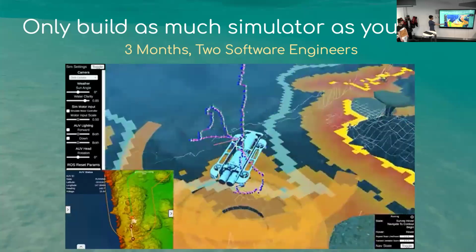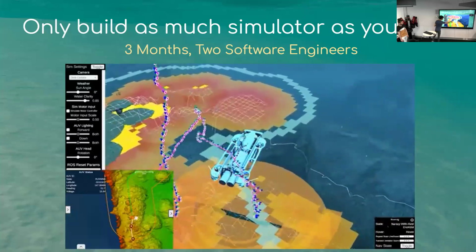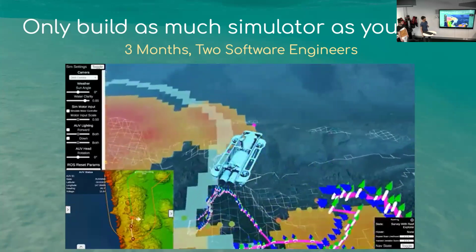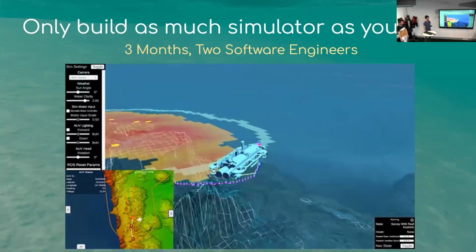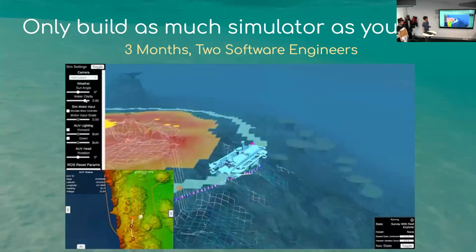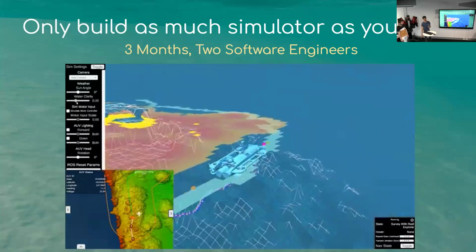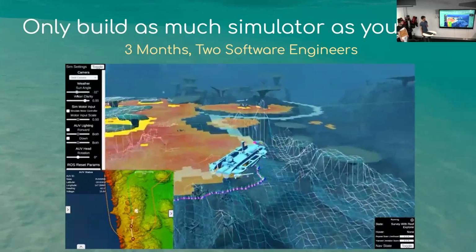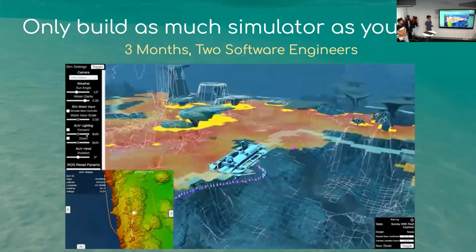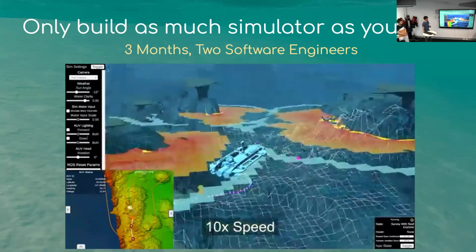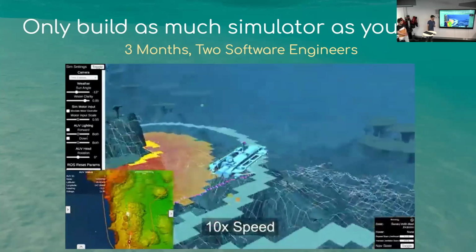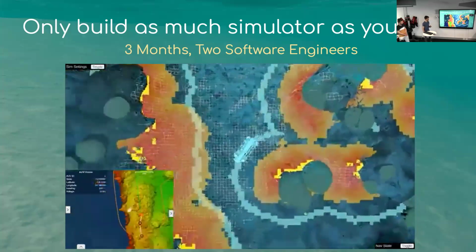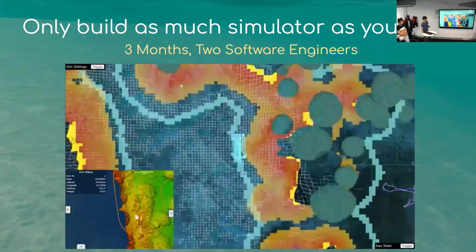So we can see here that the depth we want is where this visualization is. And that's the big boon of custom simulators, is that you get access to whatever you want in terms of visualization, which can be very helpful for debugging your robot's very unique behaviors. But in this case, it has reached its target depth and is simply gaining information about the reef over time and then deciding which is the next point, which is most advantageous for following the path on the reef and least likely to get itself into harm.